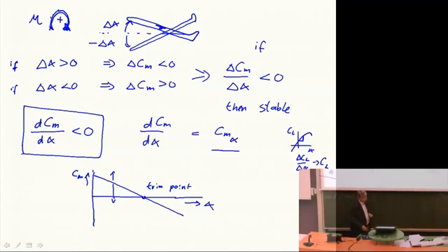Well, let's look at the trim angle and the horizontal surface a bit closer, because that is key to providing longitudinal static stability. It's all about the horizontal tail surface. The size of the horizontal tail surface is mainly determined by making the aircraft longitudinal statically stable.